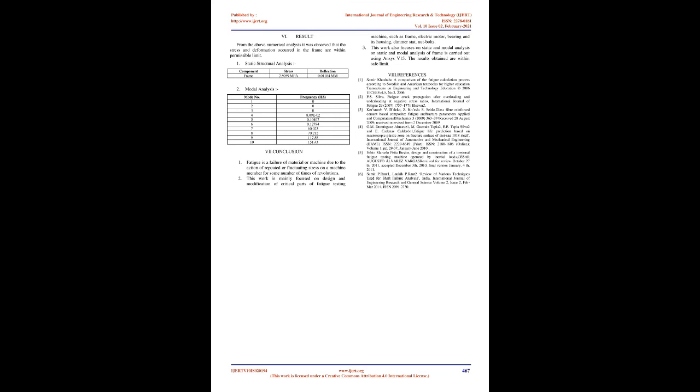Finite element analysis. Two types of analysis are performed on the fatigue testing machine. As the machine undergoes vibrations due to the motor mounted on the frame, it is essential to estimate natural frequencies of machine parts and vibrating bodies to avoid their resonance conditions, and also to determine the displacements, stresses, strains, and forces in structures or components caused by loads that do not induce significant inertia and damping effects.